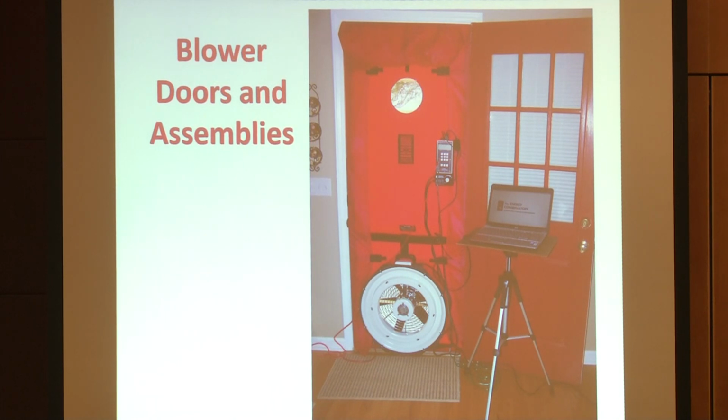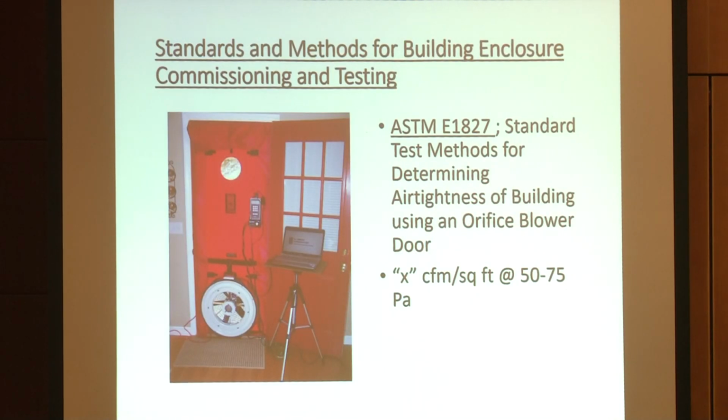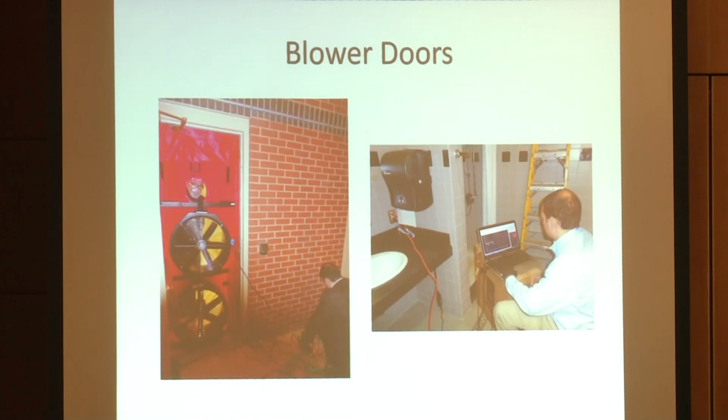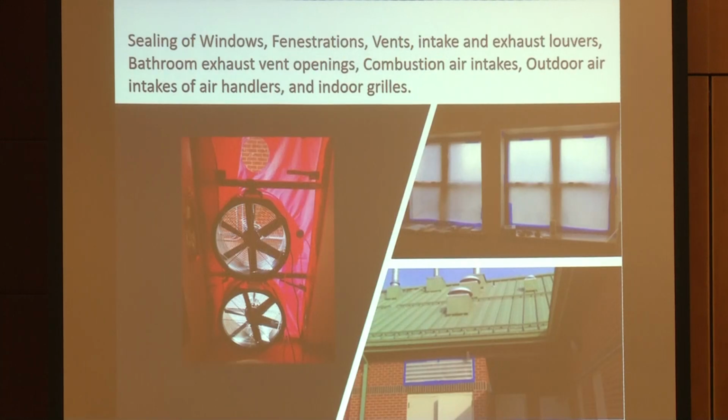Really interesting process. Very interesting doing it. There's a typical blower door there, and another blower door there. This is a job that we did on an Army base where we compared two buildings. So we did put the blower door on there. Then you have to seal all the windows, seal all the exterior. You have to seal all the grills in the building, because when you blow up the building, you want to see how much is leaking through the infrastructure of the building, not the air vents and the air handlers and all that stuff. All of that has to be sealed.